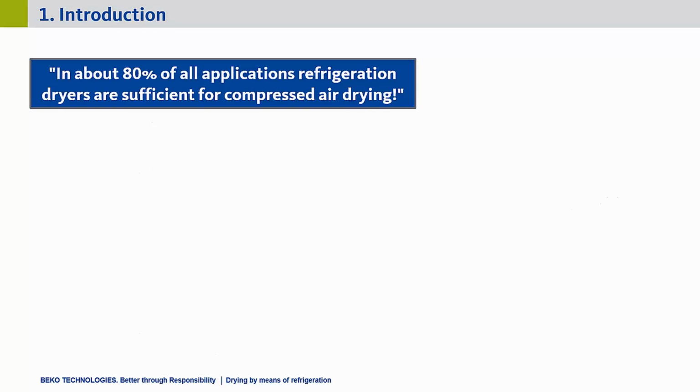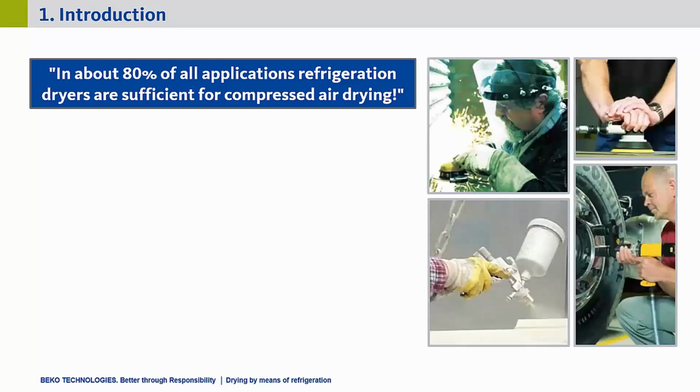And what applications are these? These are, for example, applications such as those in our own production. So when only compressed air-driven tools are required, such as screwdrivers, grinding machines, or similar. Also for simple painting and priming work, the refrigeration dryer can be sufficient. For example, if it is only about applying coatings and not necessarily about an optimal surface appearance.